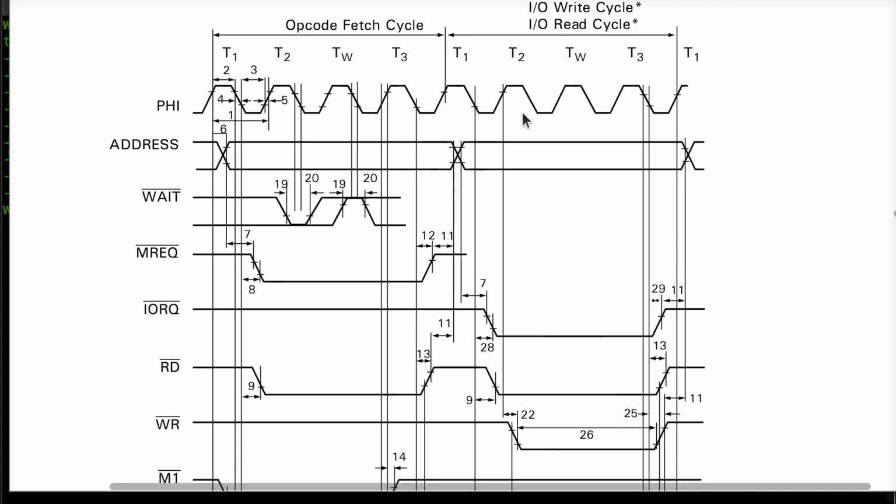of this clock. So in a simple-minded way, I'm going to create a signal that becomes active, because I'm going to use positive logic inside the FPGA so I don't have all this upside down junk to think about in my source code. I'm going to have an IOREC underscore read or something like that, and it'll go active when these two are both true, which could happen as late as the rising edge of T2. Then I want it to stay active until I see the first falling edge, which will be the falling edge of T2 right there. Then I want it to go false again.